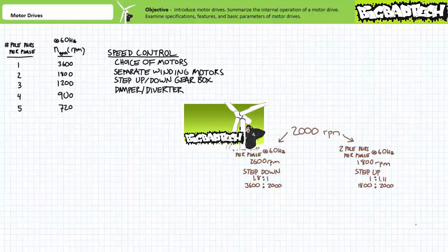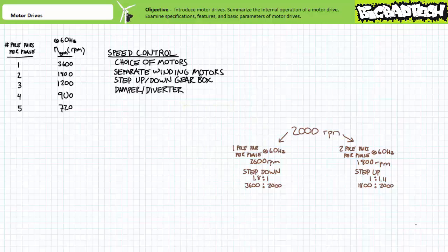Given flow rate, a measure of volume per unit time, is a product of volumetric displacement per revolution times revolution per unit time, a pump with a fixed displacement value, operated at a fixed speed, will always produce a constant flow rate. Long story short, flow rate is a direct reflection of rotational speed. A separate winding motor might be able to produce 2 distinct flow rates. However, what we really want is infinitely precise tuning depending upon conditions.